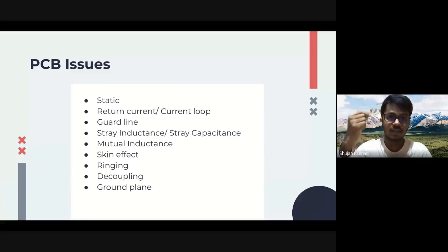These can induce noise, and at some frequencies of your noise, it can attain a high Q factor, or go to the resonant frequency, and this is called ringing. So how do you reduce ringing? You add a series resistor in between the tracks at some points, local resistors. What they do is increase the impedance, but the Q factor, if you see the formula, is divided by R, right? So it reduces the Q factor, so the damping factor increases, so the noise dies off. That's how you reduce that.